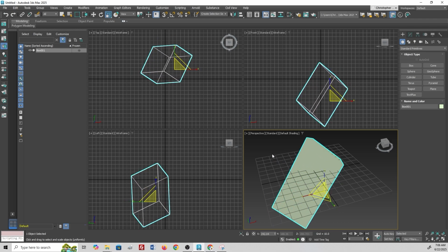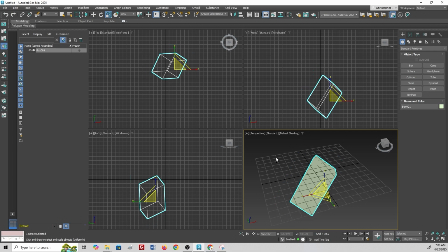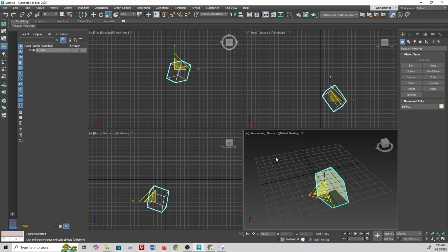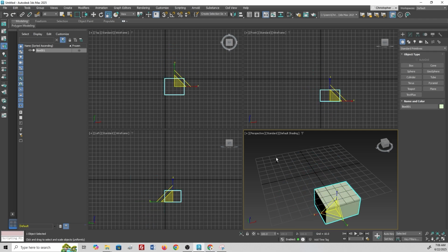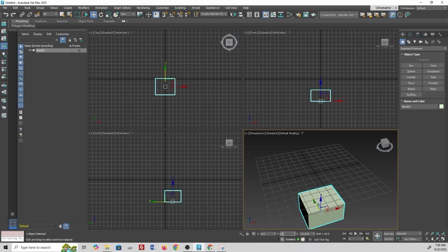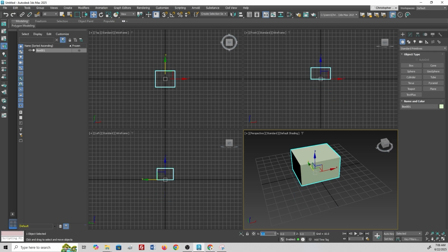All right. If you make a mistake while doing this, you can always remember to press Ctrl Z. And if you want to move things back to the origin, down here at the bottom, you can actually set all of these. Let's make sure we're on our move tool, and then press in these three buttons. You can press 0, 0, 0, and it brings it back to our origin.